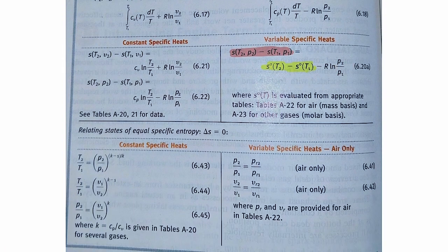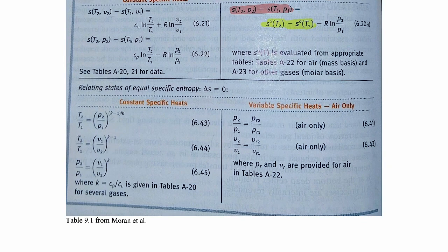And then, since we're going to be assuming for some of the processes adiabatic and internally reversible, those will be isentropic. And so here are some expressions relating properties if you're dealing with a perfect gas undergoing an isentropic process. And then here are the expressions if you're dealing with an ideal gas undergoing an isentropic process. This is where these relative pressures and relative volumes show up. So this is from table 9.1 of your textbook. All right, with that, I think we're at the end of this lecture. In the next lecture, we'll get to the Otto, diesel, and dual cycles.